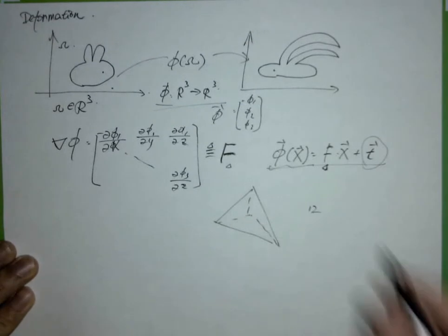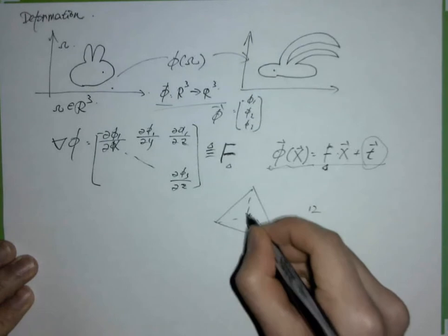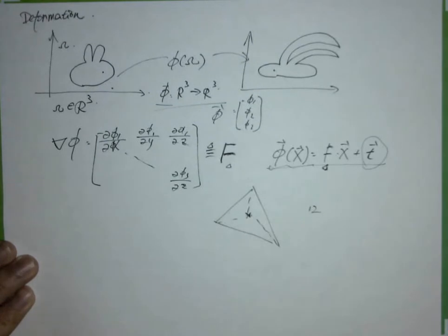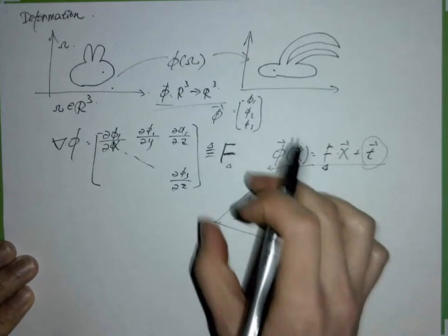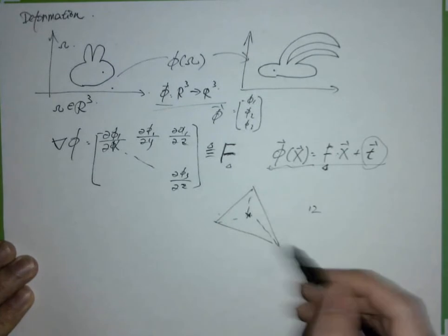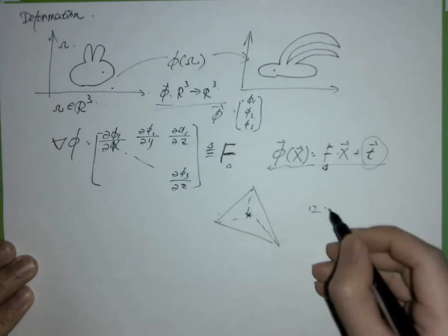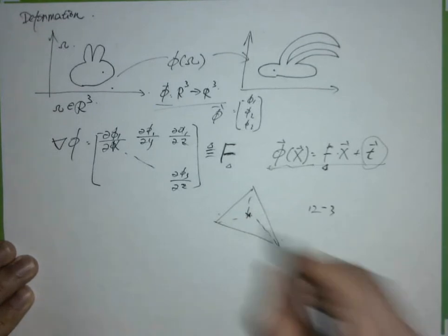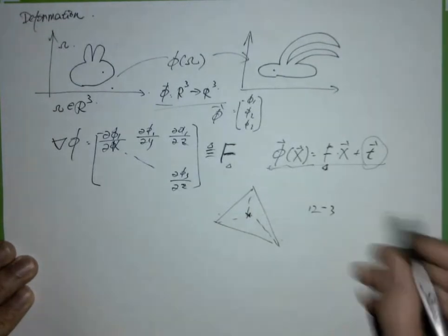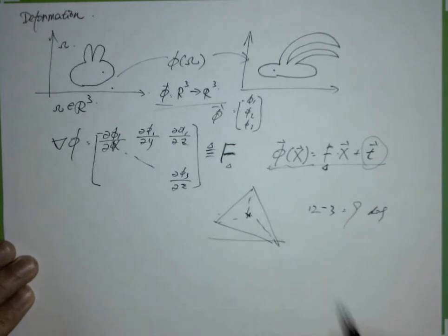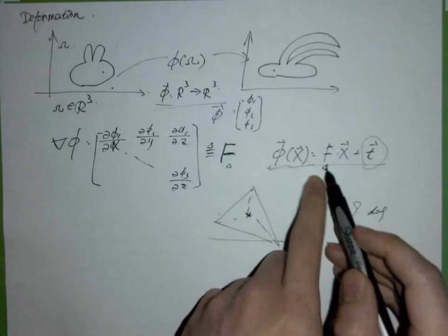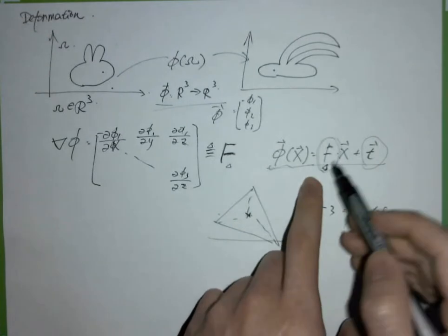But we can see that we can fix a point here, and I only care about the relative position of all the three neighbors. So we can rule out 3 degrees of freedom by ruling out the entire translation, and only get 9 degrees of freedom of this element. And those 9 degrees of freedom are in this transformation, the deformation gradient matrix F.